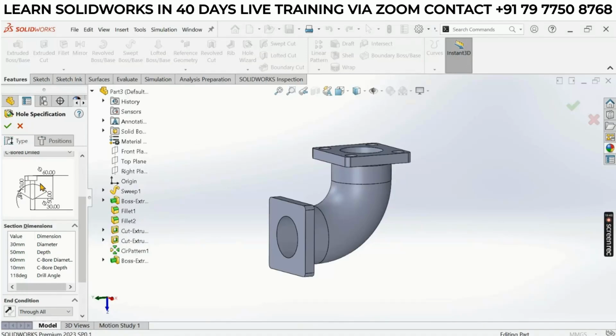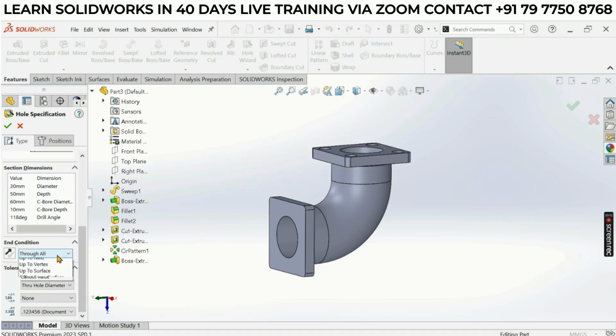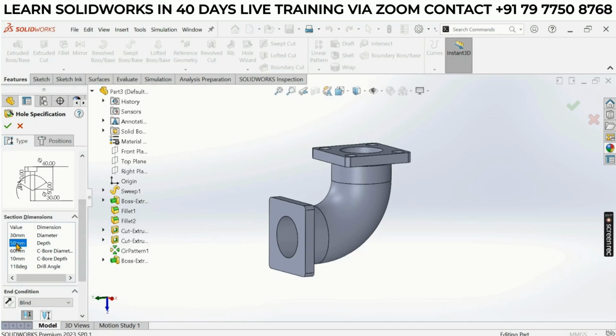Okay, just see this dia. Maximum dia is 60. Okay, yes, we want 60 only. And minimum dia is 30. Yeah, it's 30 only. And the depth for the counterbore is 10 mm. Okay, it's 10 mm. Fine. And we don't want through all, so we'll be blind and 50 mm depth here. Also, we can give the 80.